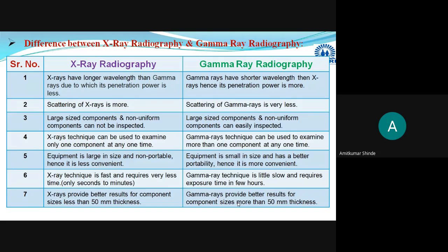Before concluding, I will tell you about neutron radiography, which I told you at the start is not in your syllabus, but neutron radiography is there. The source used is the neutron. Neutron waves we are using as the source, and that technique is used to find defects in a metallic or non-metallic component, but especially where we are using assemblies.